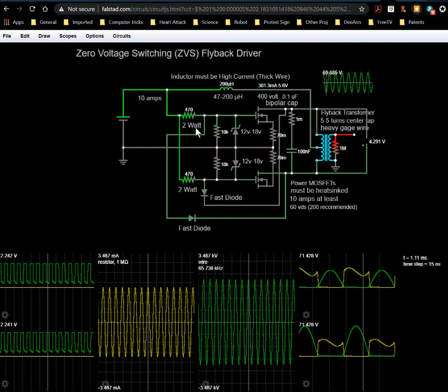Now across it, it still has 24 volts, and since it does have a resistance in it, it's not a perfect inductor. Real wires have resistance. Because it's got resistance in it, it'll still have 24 volts across it with some maximum current flowing through it continuously. That's how you get an electromagnet. If you take a DC battery and hook it up to an inductor, preferably with an iron core in it, it will amplify the magnetic field. It concentrates the magnetic field.